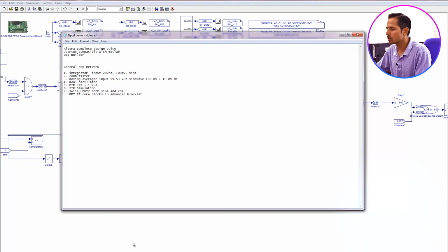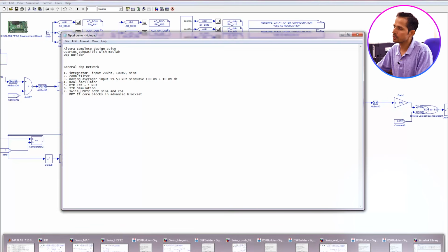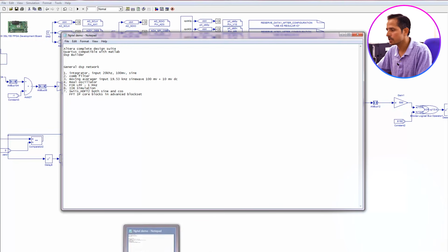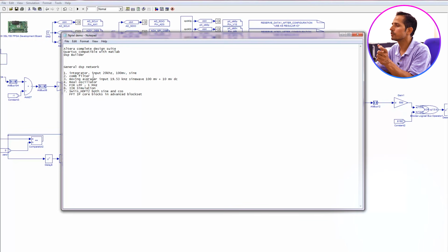So, the comb filter, as already mentioned, introduces n number of zeros into the signal. Whatever fundamental frequency I have tuned it to, let us say 20 kilohertz, it will first block the 20 kilohertz, and then further the harmonics, like 40 and so on. So for any signal I give, it should block that particular frequency first, and then also block the corresponding harmonics.